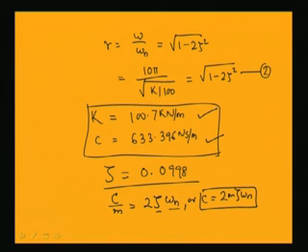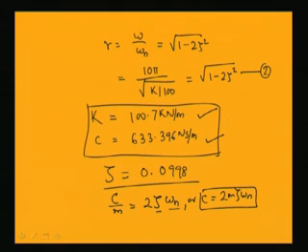In this case you have seen that we have taken a compressor, and we have modeled it as a single degree of freedom spring mass damper system. We have taken the mass of the compressor and we have found the equivalent damping C and equivalent spring constant of the system.